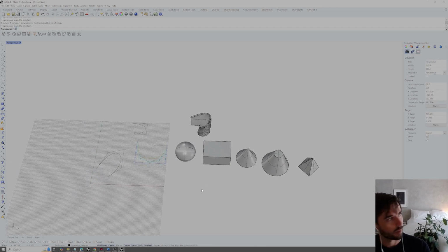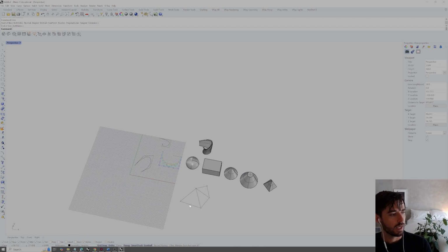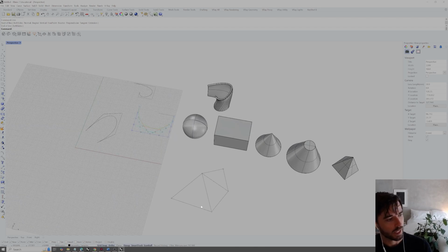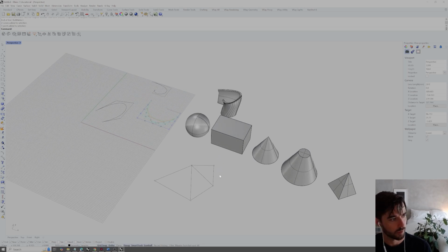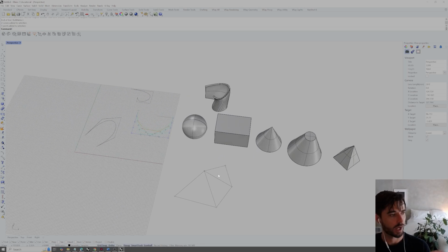So if I were to draw a bunch of points in space, and then draw line connections between each of these, and then group these, so each one of these areas that I've now enclosed would be called a face, where each of these lines would be called an edge, and each of these points would be called a vertex. So that is a mesh geometry, and it's only defined by this information. It's not defined by any additional information.